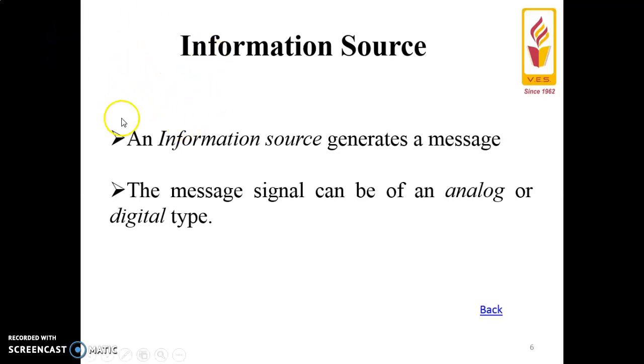But in general, the information source generates a message which may be of analog or digital type, like your audio signal, audio video signal all come under the category of analog. Your telephone signals, voice come under analog. But the data, that is the files from the computer, email, etc. come under the digital type. So if the output of the information source is analog, it has to be converted into digital by using proper encoding technique like pulse code modulation technique, adaptive delta modulation, etc.